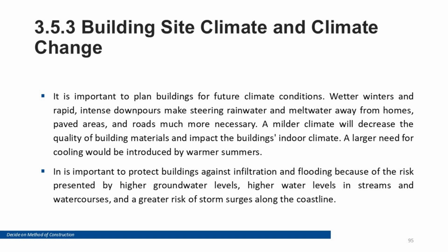Building site. Climate and climate change. Long-term resilience supports long-term energy efficiency. Heat waves, intense rainfall, and changing moisture patterns can stress the envelope. Good responses include robust shading, strong moisture management, durable materials, and ventilation strategies that can adapt to changing conditions while maintaining comfort and performance. Planning for resilience protects the building's energy rating and reduces future retrofit costs.